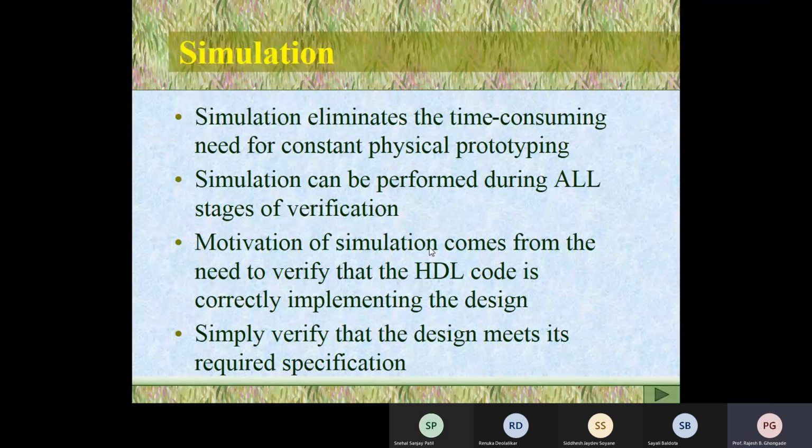The customer will say the maximum ripple content allowable at my end is this much. For example, 5 millivolts peak to peak, or 10 millivolts peak to peak, or 100 millivolts peak to peak, depending on his requirement. So he will say, your power supply should give me 5 volts if I draw 1 ampere current out of it, and the ripple content in the output should be less than, let us say, 50 millivolts peak to peak. So this completes the output specifications. Understood, guys? Yes, sir.